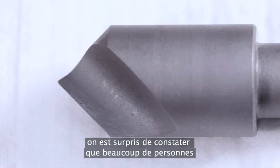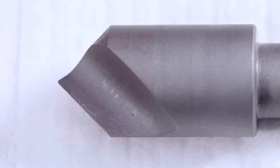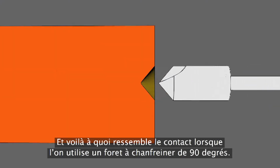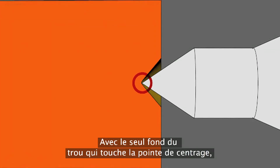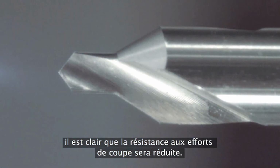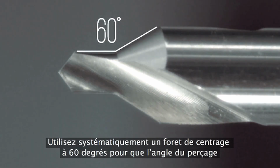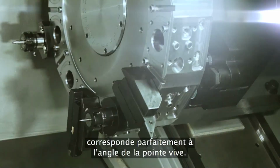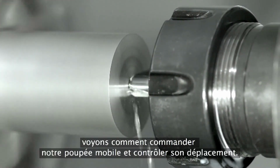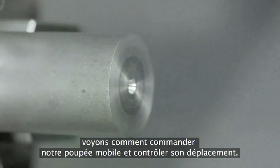And though it may seem like an obvious point, it's worth noting that a surprising number of people will mistakenly use a 90-degree chamfering drill to make their center holes. This is what the contact looks like when a 90-degree chamfering drill is used. With only the bottom edge of the hole touching the center's tip, resistance to cutting loads will obviously be reduced. Always use a 60-degree center drill so the angle of the drilled hole will perfectly match the angle of the live center.